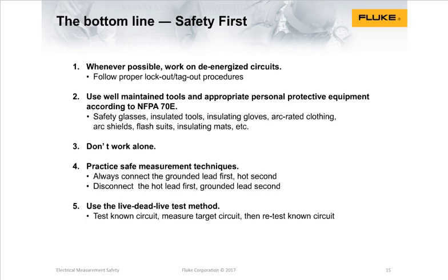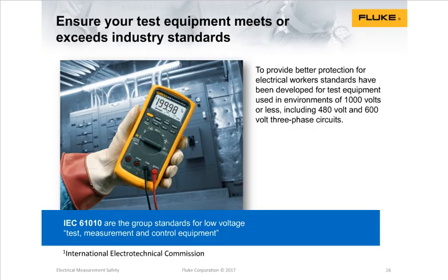And use the live, dead, live test method. Again, very important. Ensure that your test equipment meets or exceeds industry standards.